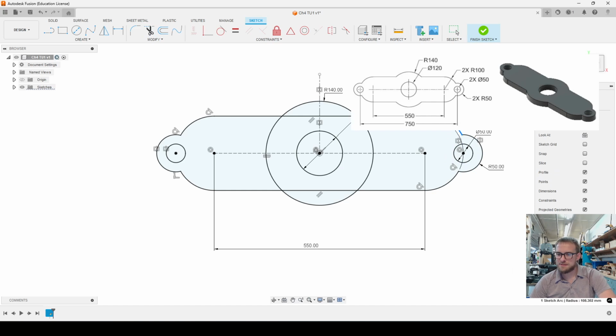So this still wants to move. Apparently it lost its tangency, so I need to add that this is tangent right here. Your mileage may vary, it may be slightly different for you, but basically when you have something blue, hit escape to not have any tools up and then drag it around and see what's going on. So I'll just go back to that. When I dragged it up here, I noticed that's supposed to be a smooth line.